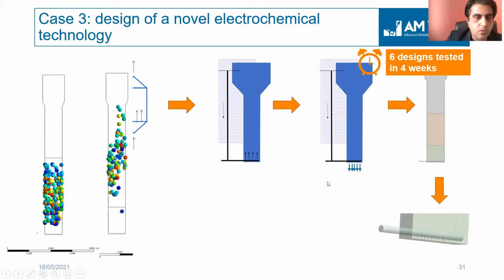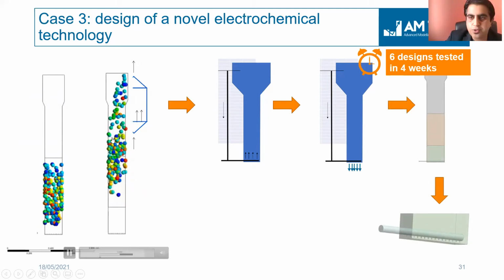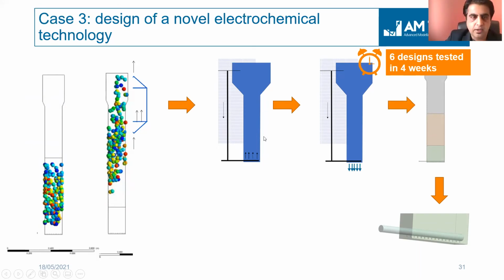And we saw that now we got the fluidization, but it was too much, and it was not very symmetrical, which was also not desired, and it will also lead to flush out of the particles or floating of the particles at the top. So this was kind of overkill. So we needed to lower it so that we can have the optimal mixing or optimal fluidization of